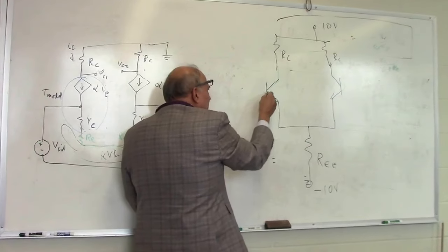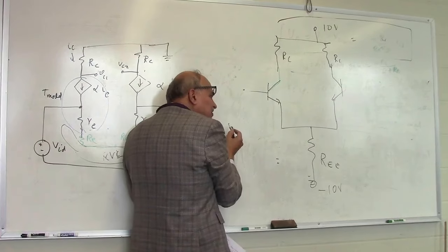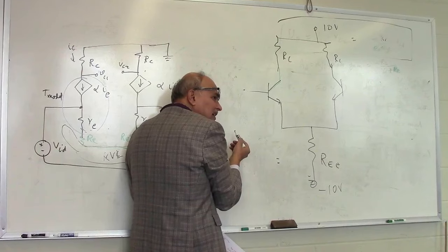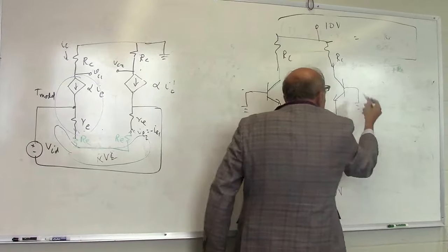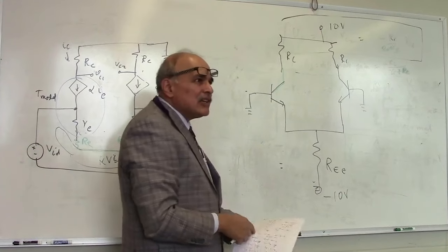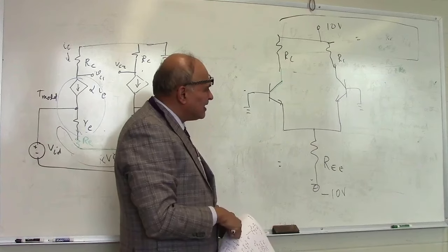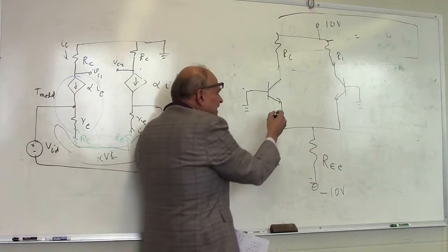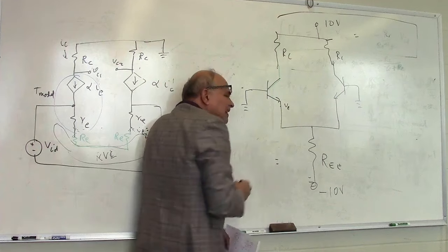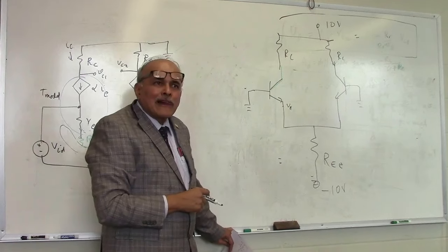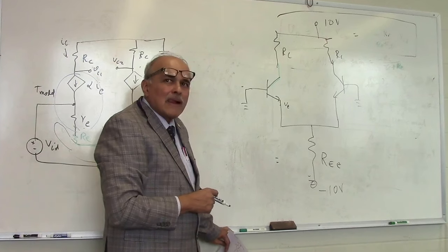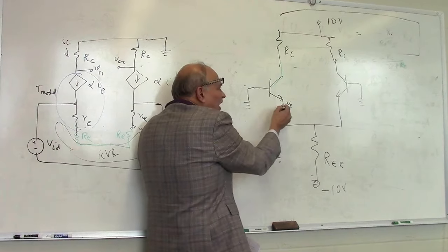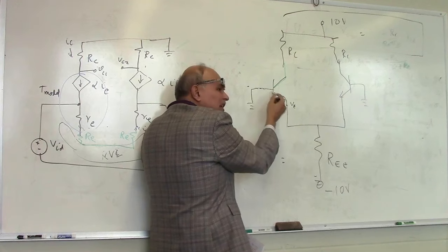So let us not apply any signal. Let's just apply a bias value. And that bias could be 0 in the absence of any differential signal. So if I apply 0 bias here, what will the voltage be at the emitter here? Guess, give me a number. -0.7. Yeah, it will be one base emitter junction drop.